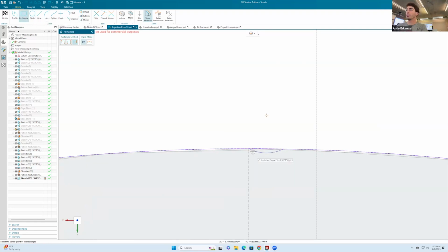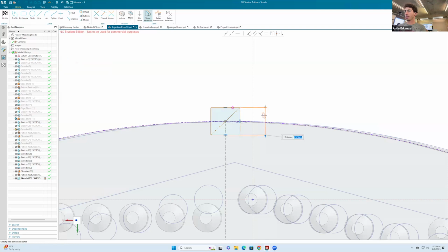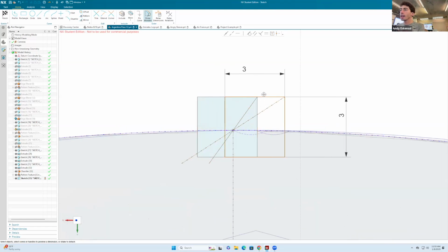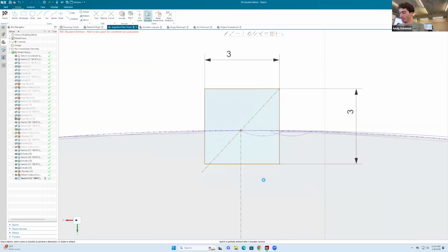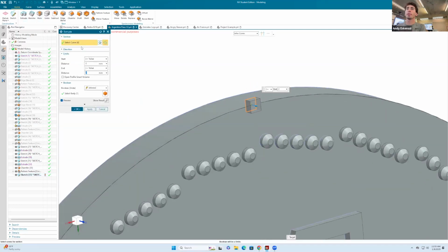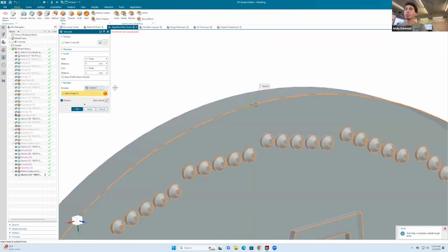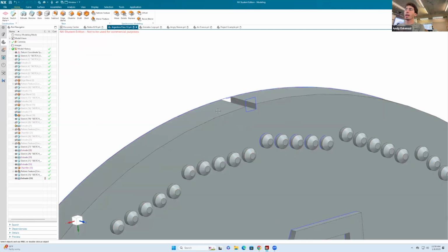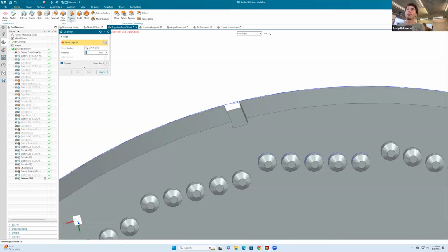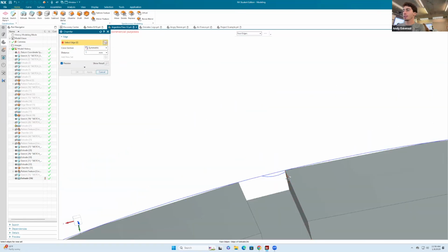So now I can go here to rectangle and I'll do a center rectangle in here. That's gonna be like this big. And I can make that 3. Can make that 3 as well. See that rectangle for some reason. Let me see if I can make that 1.5. That way it doesn't move. Okay, I'll say finish. So now what we can do is go here to extrude. I'll say subtract. What was it, like -10? I'll say okay. So now I have one of the ridges done. In fact, I'm actually not terribly happy with that design. So maybe I can go here to chamfer. And what you could do is select all of your edge. Actually, hold on. Let me chamfer, single edge.